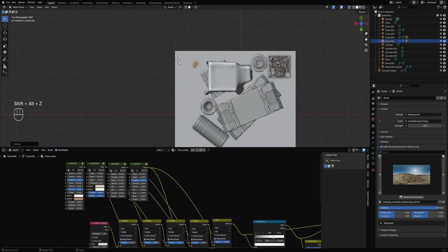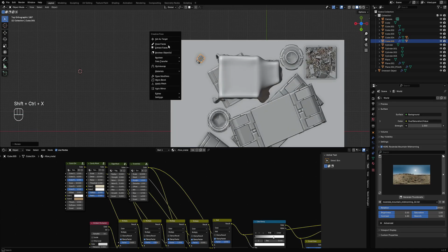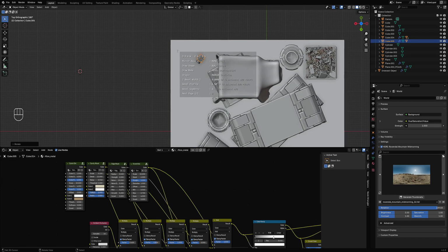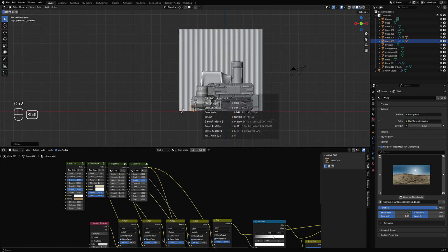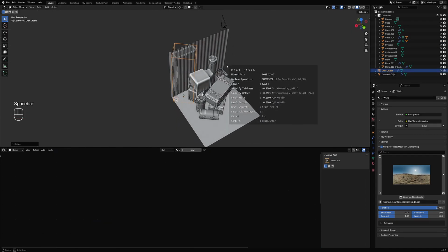Let's position the 3D cursor there. So press C in this area to make sure that it's the distance by which the draw object will be created. Press 4 for the strips and increase the thickness. Make sure to add another line, so the last line will not be considered.